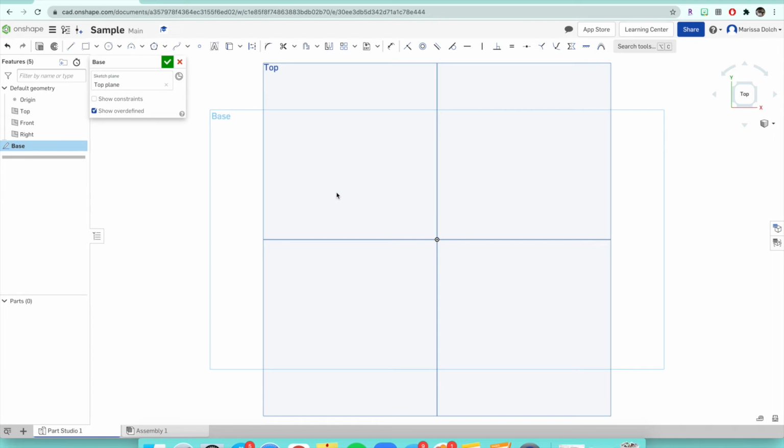So now what we're going to do is I'm going to just bring out a circle here, and this circle, actually you can put anywhere you want, but it snaps right to the middle, so I'm going to do that. Now when we're looking at this circle, you can see right now it's blue. And as I move the circle in and out, you can see the numbers on the bottom right quadrant there kind of get smaller and bigger as I go in and out. Now by default, Onshape shows you inches, so that is the diameter of the circle in inches right now.